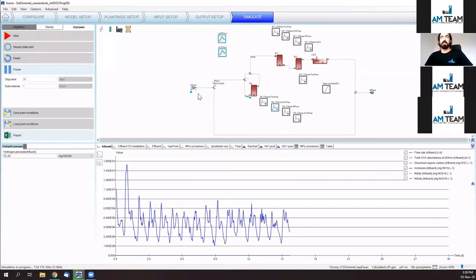What you see here, the effluent wastewater from the treatment plant is arriving to a split, which is a bypass where the high peaks in outflow are bypassed into the overall plant effluent. But most of the flow is directed to our ozone installation, which is sized to treat most of the water flow exiting the wastewater treatment plant. Now, the first thing that we encounter here is another split, which is directing 20% of the flow to our